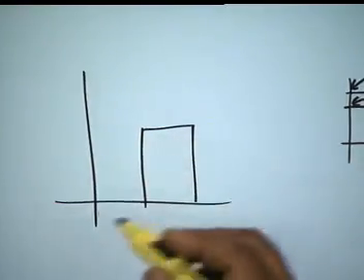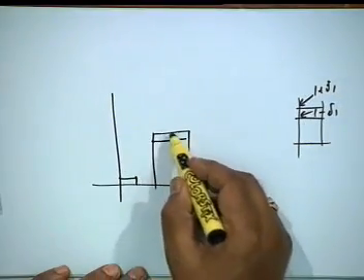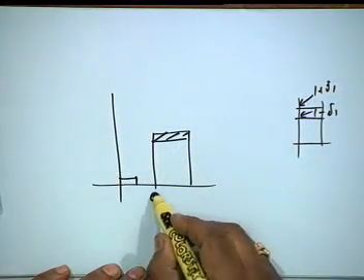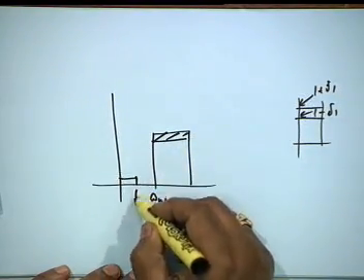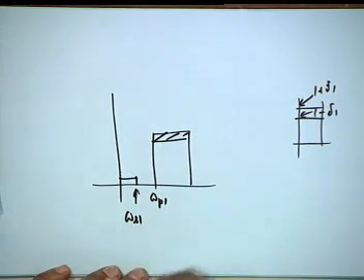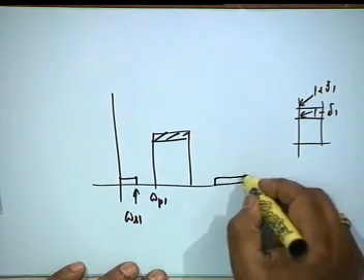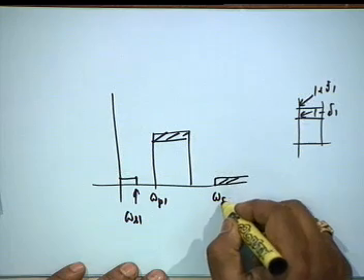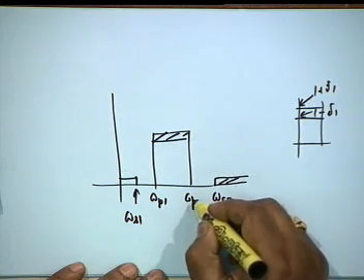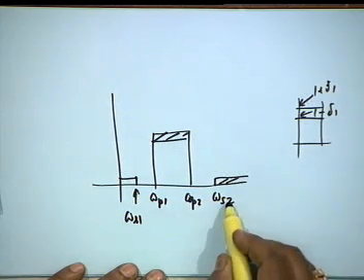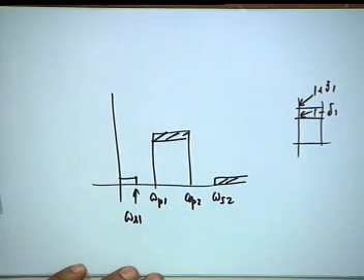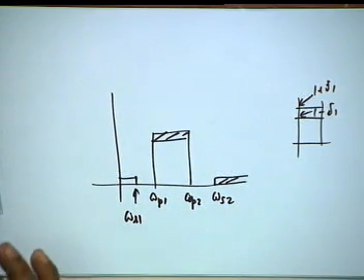In a band pass filter, it would be omega p1 minus omega s1 divided by 2 pi, and you have to make sure that these two are equal, that is omega s2 minus omega p2 by 2 pi. You have to make sure that they are equal. If they are not equal, then you have to adjust them.